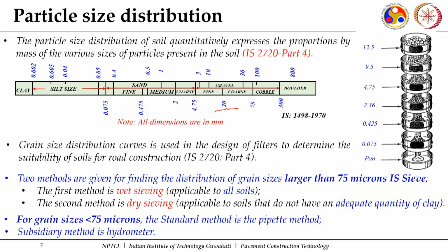Now, as I mentioned, what is your gradation or soil size distribution? I can pick up the sieves where the material is expected to lie. So, if a material has sizes ranging from, say, 20 mm and going below, even lesser than 1 micron, I try to do sieve analysis accordingly.